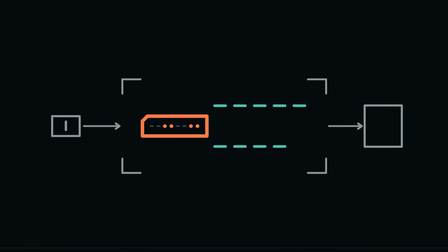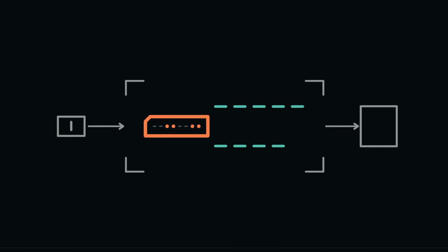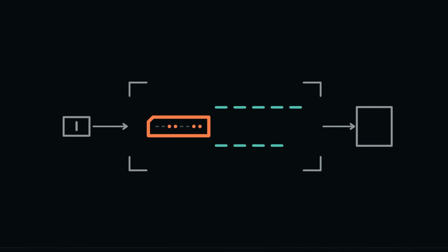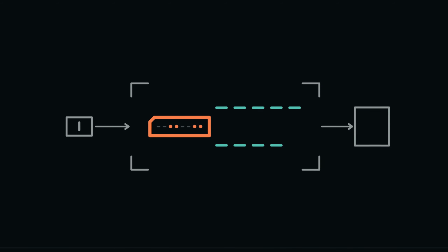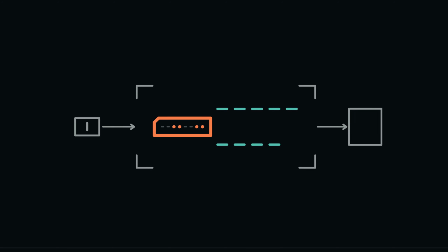Our SE8 program waits by polling. It loads the keyboard status register, compares the result with 0, and branches back when no byte is ready. Polling is repeated observation by ordinary instructions. It is useful when the program can afford to check often or when the event is expected very soon.